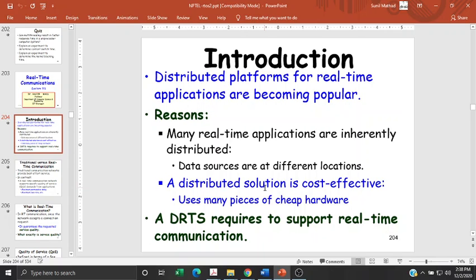The phonetic notes have to overlap so that there is continuity. If there is a larger break, maybe due to your processing algorithms, because you are digitizing and compressing, and because of the limited bandwidth you are sending it onto the network and it is reaching the other end, and either through network delay or processing delay you exceed 1 by 10th of a second, then there are idle periods. I'm not saying the reception is not intact. Data is received, but the reception may have more delay than 1 by 10th of a second, or the persistence of hearing.